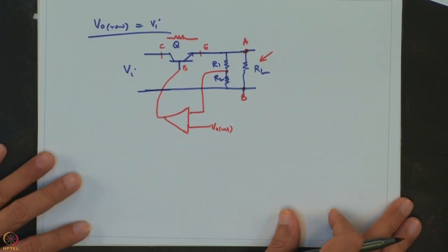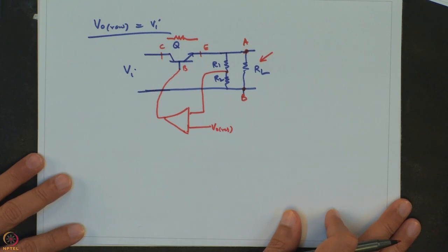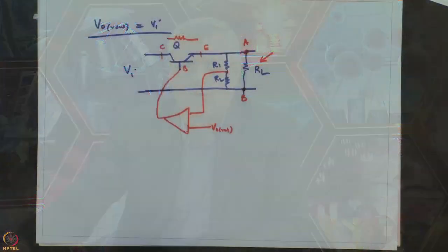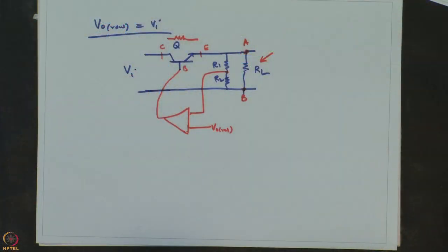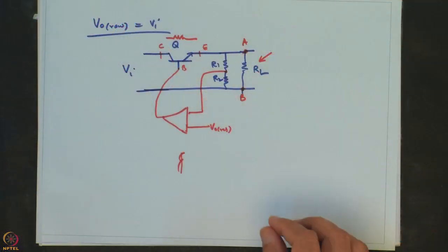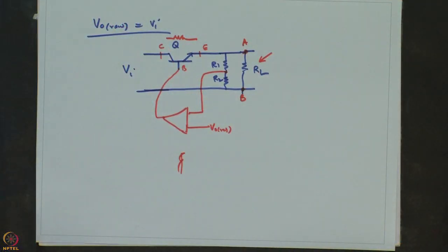It is very common for these linear regulators to be realized as what are called 3-pin regulators. There are 3-pin 5-volt regulators, 3-pin 15-volt regulators, and these are all standard voltages. One of the reasons we call it a linear regulator or a linear supply, as you might have guessed, is that the transistor is operating in the active region, which is the linear region. So, let us say we have a 3-pin regulator,